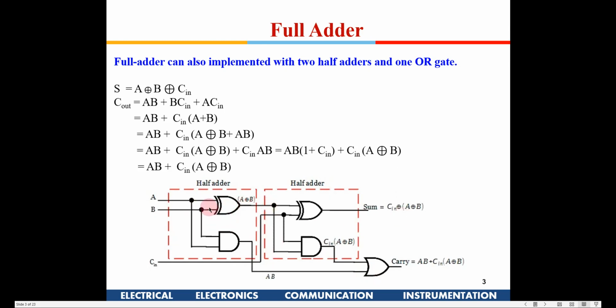If you see here, 1 gate delay, 2 gate delay, 3 gate delay. Whereas sum is just 2 gate delays. But carry needs to be propagated to the next stage, right? So this is not a very efficient way of implementing a full adder.